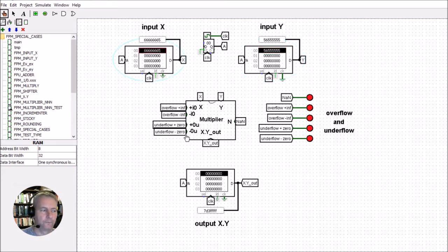So that's all there is for the multiplier section. There's a couple of things I have to add. Like I said, the correction injection for the subnormal rounding, and I'm also going to add one other output, a flag that's going to show us whenever the multiplication is an inexact multiplication.